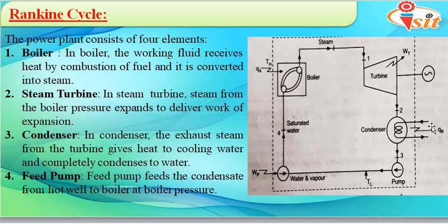So here there is one more component which we call the cooling tower. So the cooling water is obtained from this cooling tower and it is circulated through this coil which is placed inside the condenser. And as this cold water is circulated, at the same time the hot steam from the turbine enters the condenser, so a heat exchange process will take place between these two fluids.